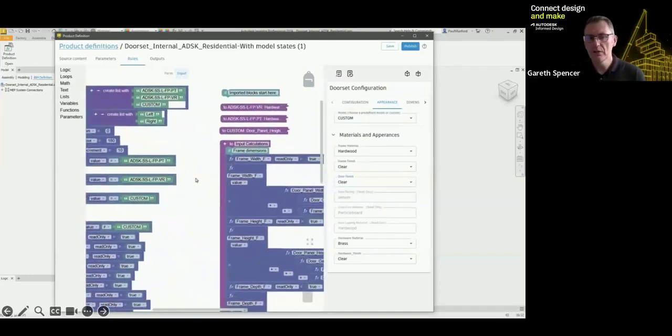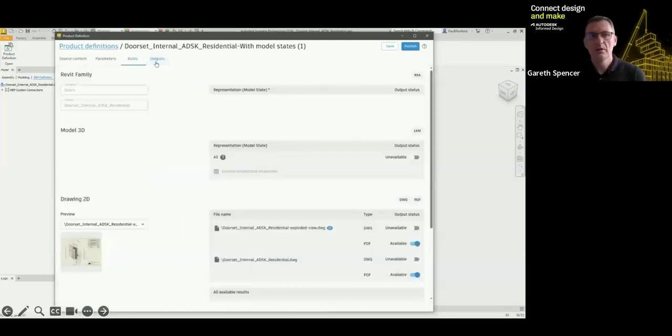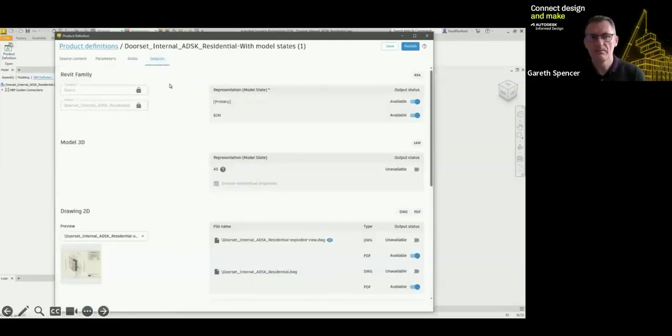This can read the iLogic that you've placed into your model as well, so you can control the object in the ways that you need it to, for example the length, the width, the height, as you need. Setting the constraints in here will allow the Revit user to work within those boundaries rather than having to remodel from scratch.